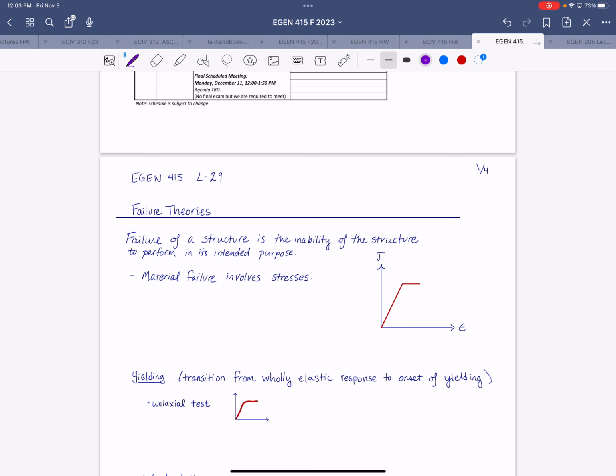Then set up Castigliano's method to solve for the reaction at the location where you relaxed the force, by setting up those integrals with respect to the partial derivative of that force, and then set that deflection equal to 0, since if you're doing the roller support, you know that the deflection here is 0.